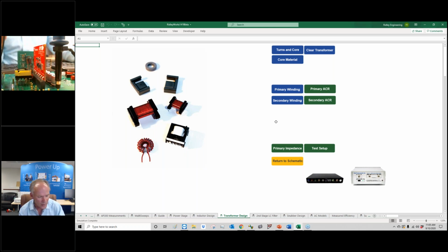Now, if you've got a one-to-one winding, it's good because you can wind it bifilar. And then a toroid does a lovely job and it gives you low leakage, but of course it's more expensive to wind. So every case is different. Sometimes we might look at a toroid. Some of the aerospace customers want a toroid. So it's like, sure, but let's try and range the turns count to make it a nice integer that we can wind bifilar or quadfilar and then connect series parallel to get the turns counts that we want. So you can do that kind of thing. Hope that answers it.